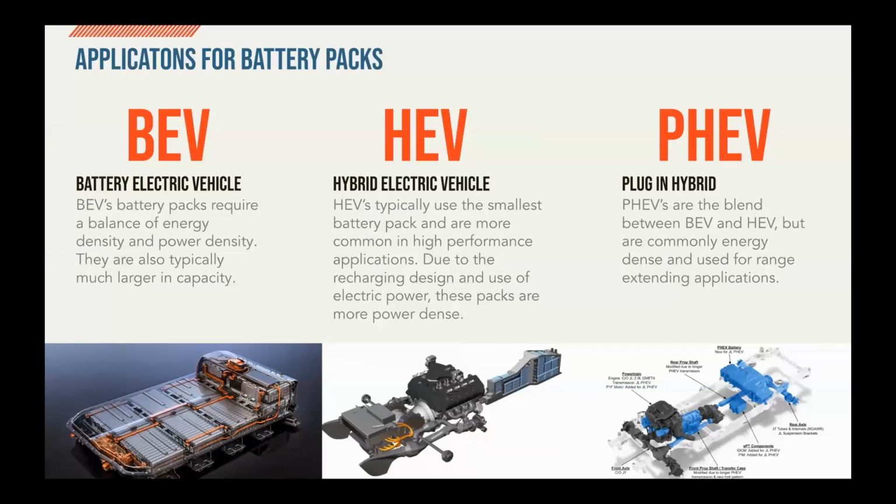But they have the most advanced battery management systems, cooling systems, and power distribution for the vehicle, and they're responsible for powering everything in the vehicle at the chassis and the body level, including the powertrain. So not only the motors, but they also provide 12-volt power through a DC to DC converter.